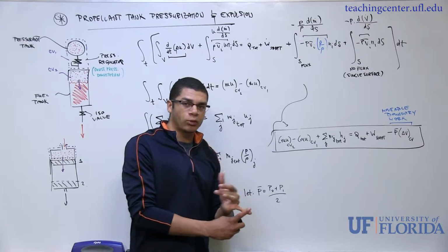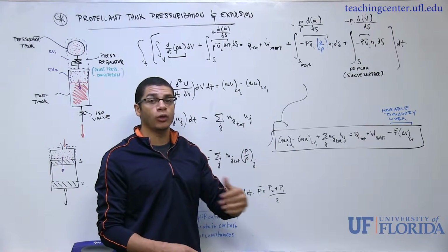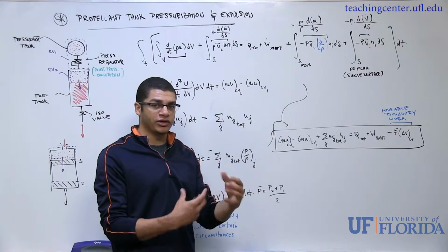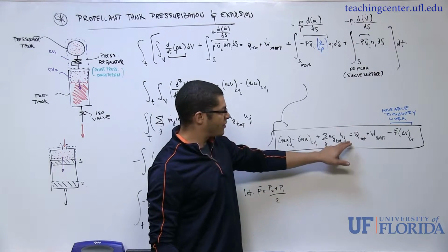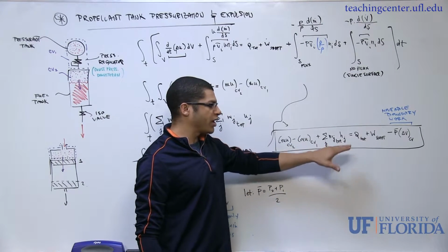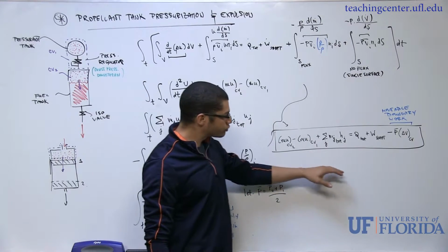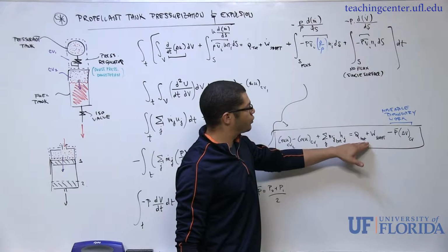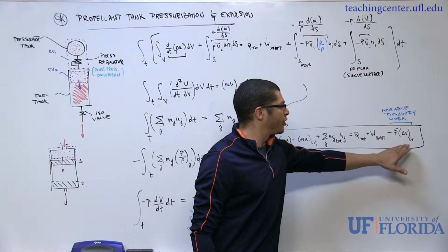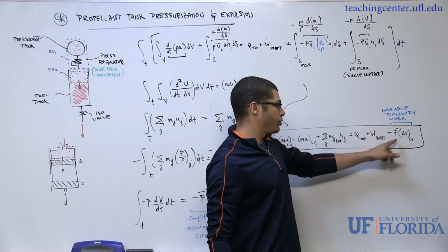And we've assumed, again, that that was not an unsteady process, that the enthalpy flowing in or flowing out was going to be constant with time and also constant over the entire cross-sectional area. So we just have this H, which could be pulled out. Actually, not pulled out, but again, Hj is going to be a constant associated with each particular inflow or outflow. Then we've got the total amount of heat transfer, the total amount of shaft work or other types of work besides boundary work, and then finally the movable boundary work, so minus P average times delta V CV.